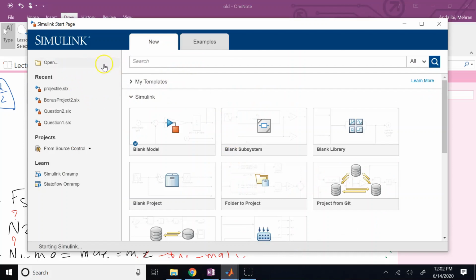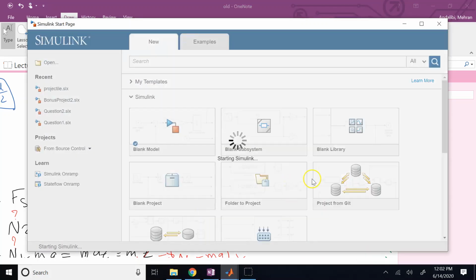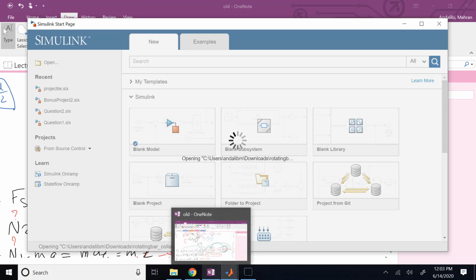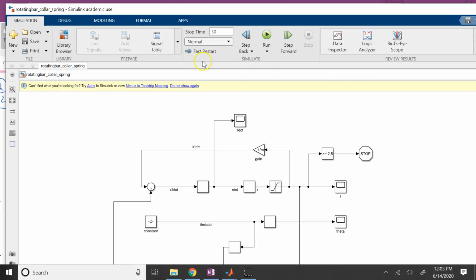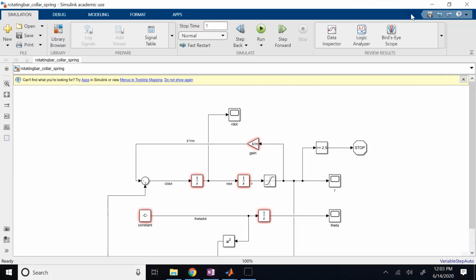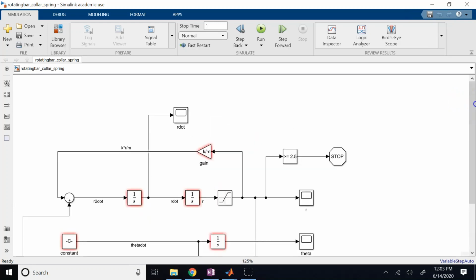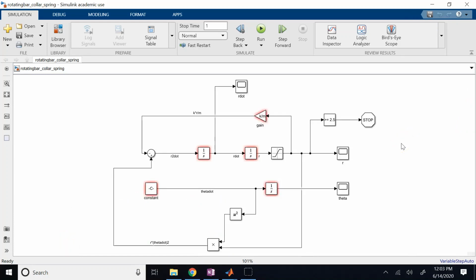And then it gives you back R and R dot to the workspace so that you can get them, you can plot them, and do whatever you want. Okay, so let me show you that. Now, since your theta dot is constant and your initial theta, you assume it to be 0, then you can find the theta at any other point, right? Because it's just uniform angular motion. Theta of 0 is 0, theta dot is fixed, so theta at any other point is simply omega naught times t plus theta at 0. And that's what you can see here. Constant omega is integrated, given some initial theta 0, and then sent out to the oscilloscope and also sent out to the workspace for the sake of plot and animation.